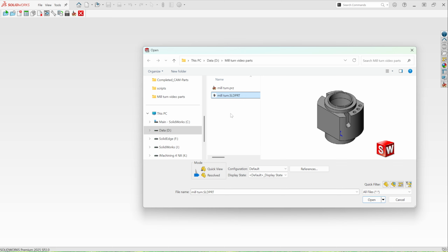Now, if you have a choice between file formats to use, you may want to select the most advanced file type option. What I mean by this is that if you could pick between a .sldprt file or a step model of the same part file, the .sldprt file may contain more information that can assist you in programming certain features.